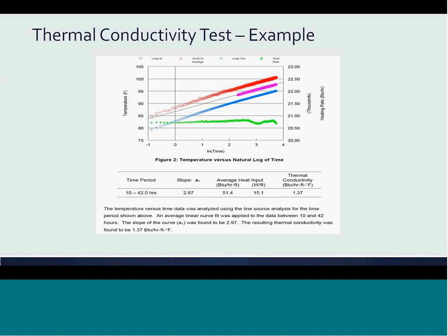The circulation pump is turned on and water is circulated through the test loop. Data is collected every 5 or 10 minutes. The water temperature is measured for 30 minutes or so, so that a deep earth temperature may be determined. After this, a heat source is connected to the water, and the data log measures the temperature at both the inlet and the outlet of the test loop.